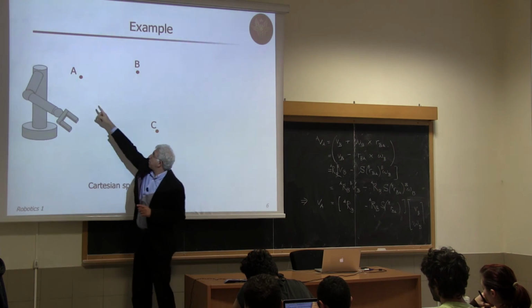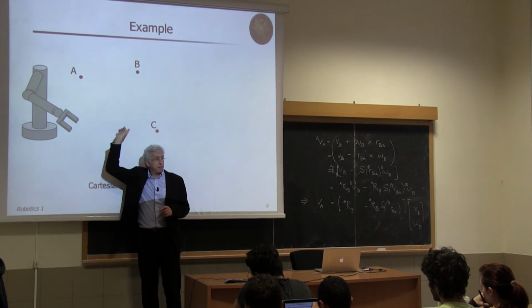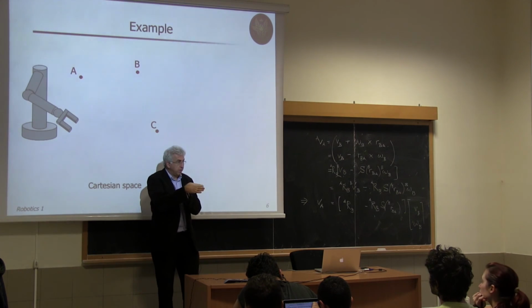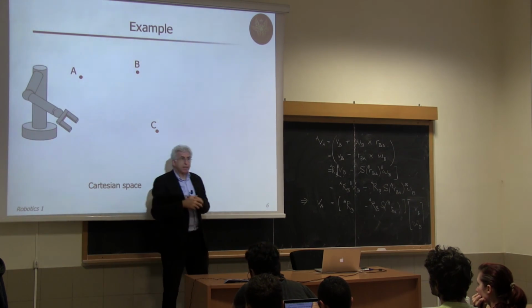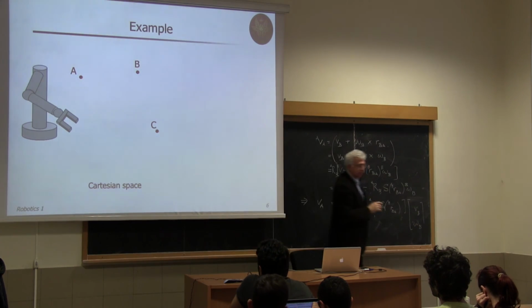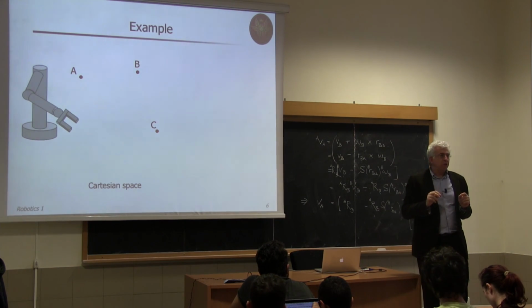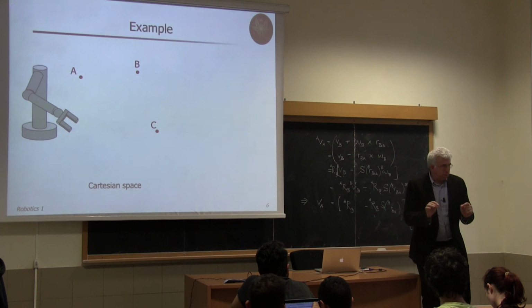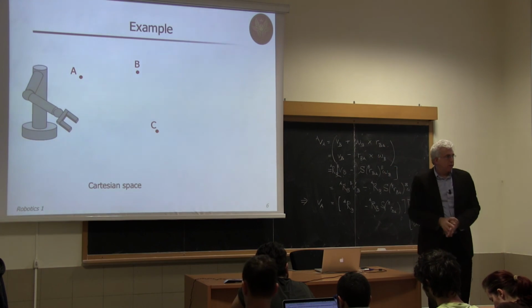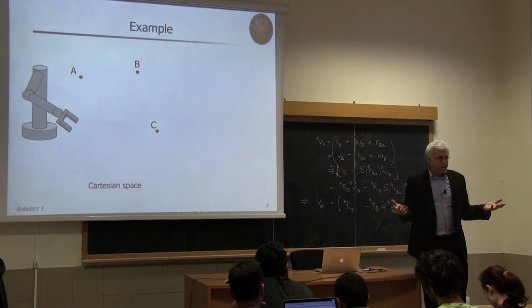Because if you're moving from A to B in a straight line, when you reach B, you have a velocity pointing in that direction, and all of a sudden you have to switch velocity to the next point, and this jump in the planning of velocity is not really nice, like we have seen before. So you're forced to reach B, stop in B, and then restart from zero velocity pointing towards C, which will make the whole cycle longer.